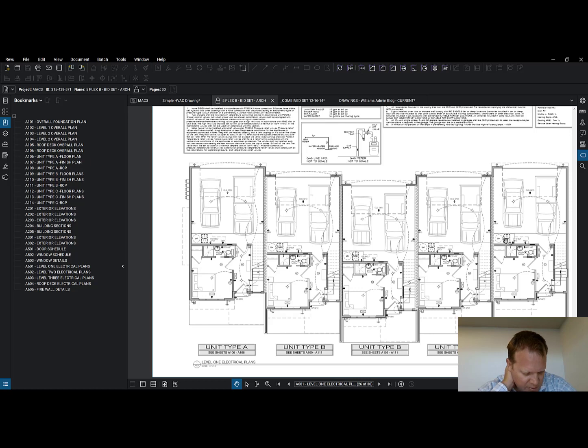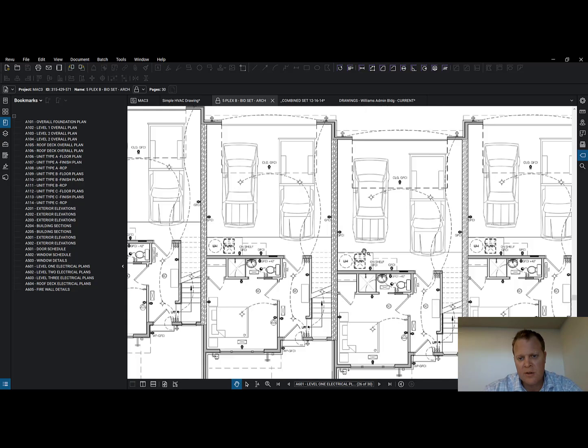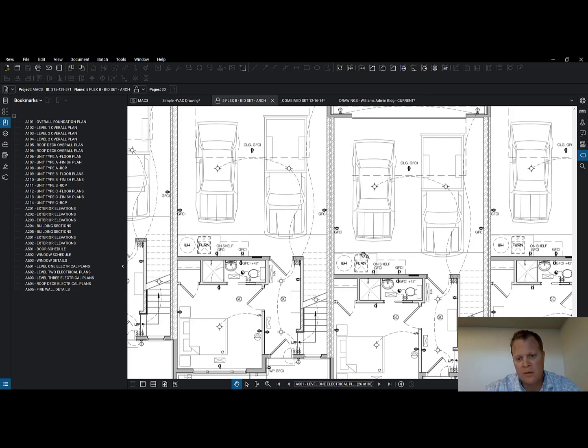Because just the ignition source has to be 18 inches off the floor. But a lot of times I see the entire mechanical platform raised in the garage. And the appliance has to be protected from impact, so it can't just be sitting there without any protection, ready to get run into. So that's sort of like they have to frame this in or something like that.